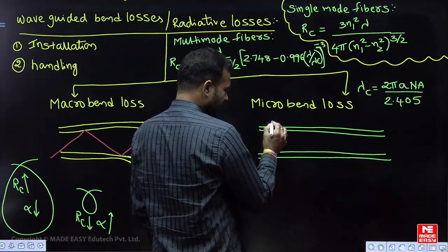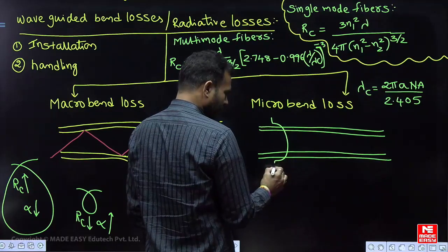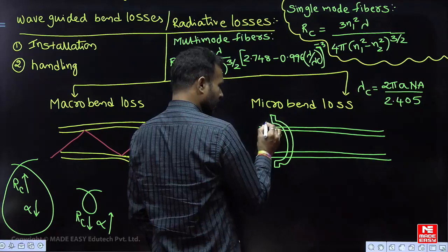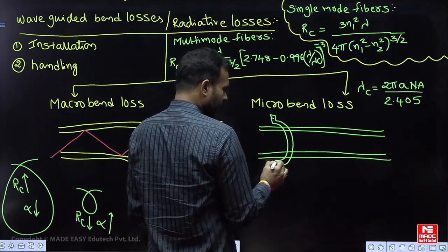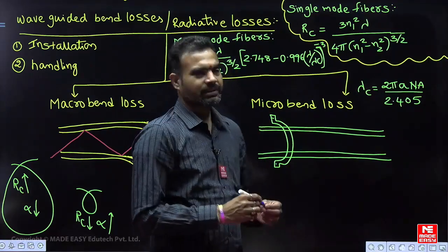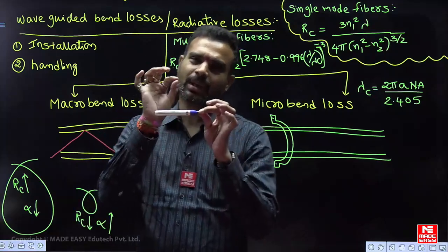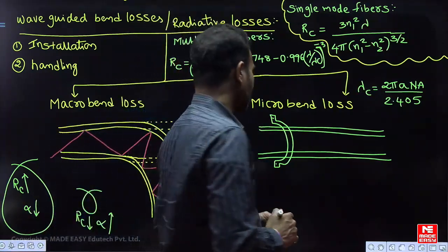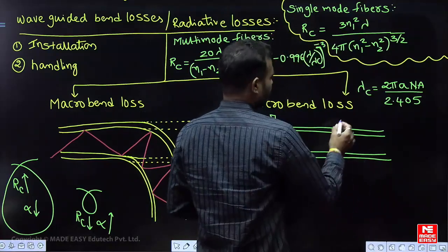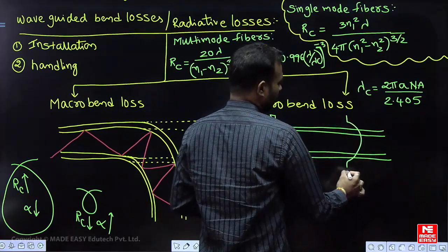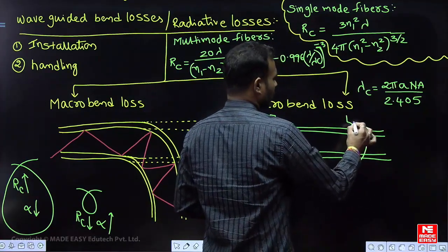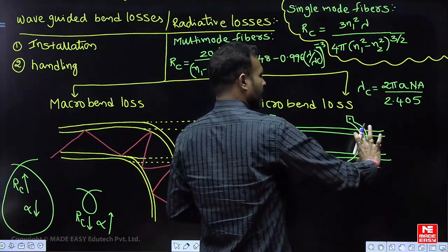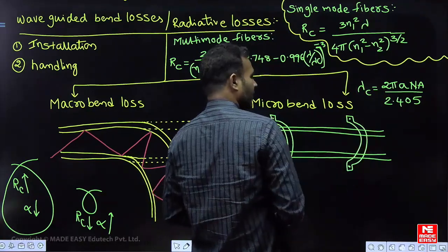So this part was given like this, clamped. You are clamping the fiber, clamped to the wall. Sometimes you can see some of the wires are clamped. For copper wires, if you clamp them there are no issues, but if we clamp fiber optical cables, it creates a big problem. Because of this clamping, the fiber is clamped to the wall like this. Whenever we clamp it by putting a nail, external pressure falls on the fiber.